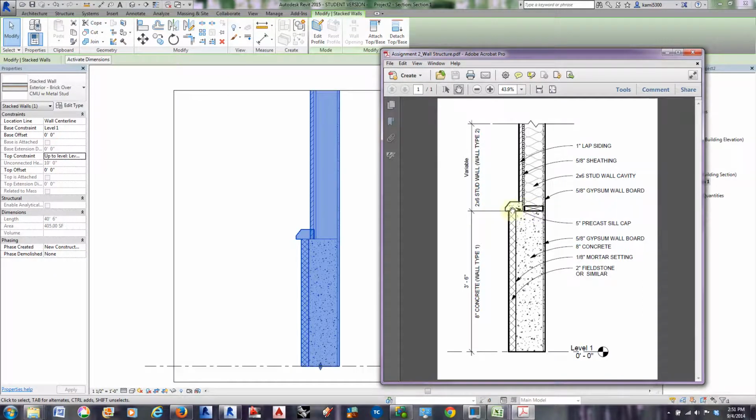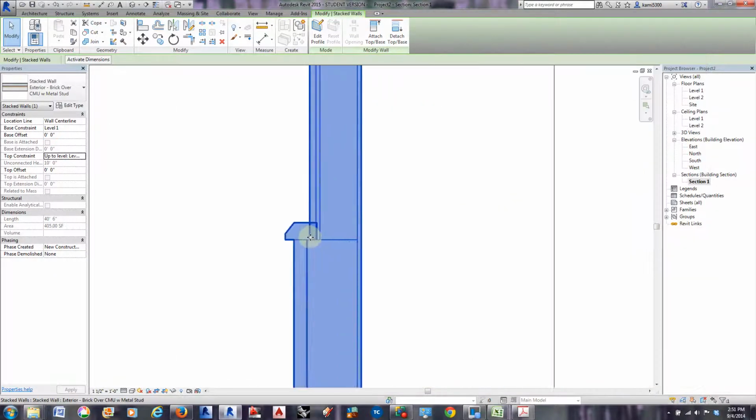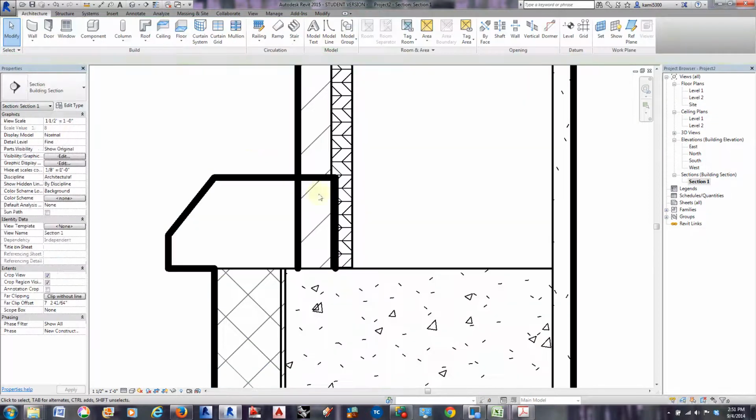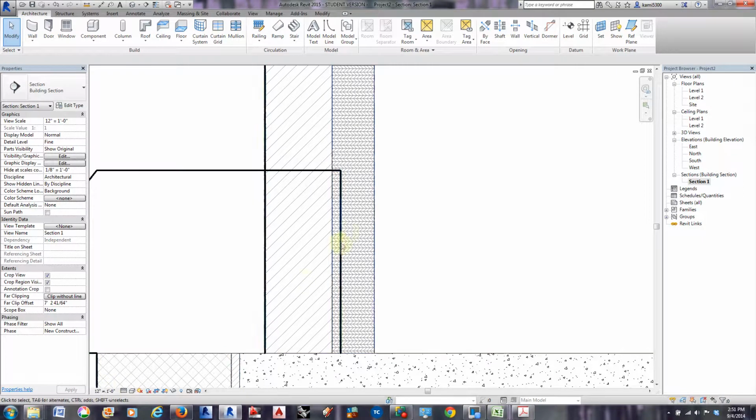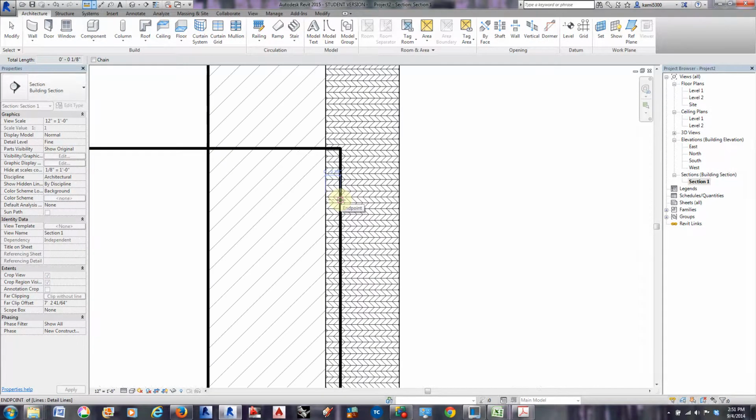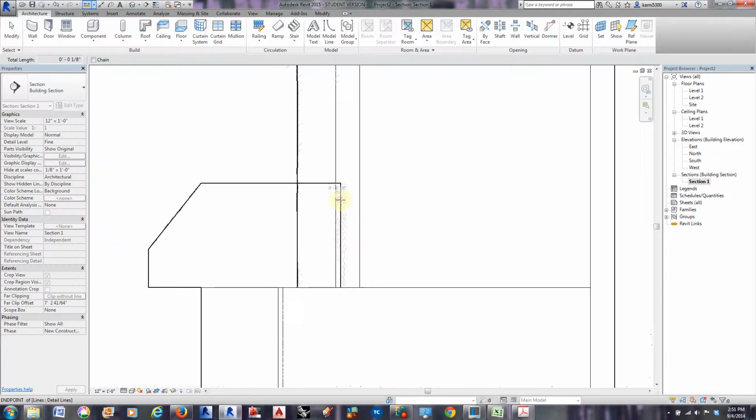And then if you look really closely, you'll see that this guy is also cutting into our plywood. And so just to figure out how much it is cutting in, I switch my viewport to 1:1. I'm going to use the measure tool and measure this, and it's about 1/8 of an inch. And it's not really where we want it to be.